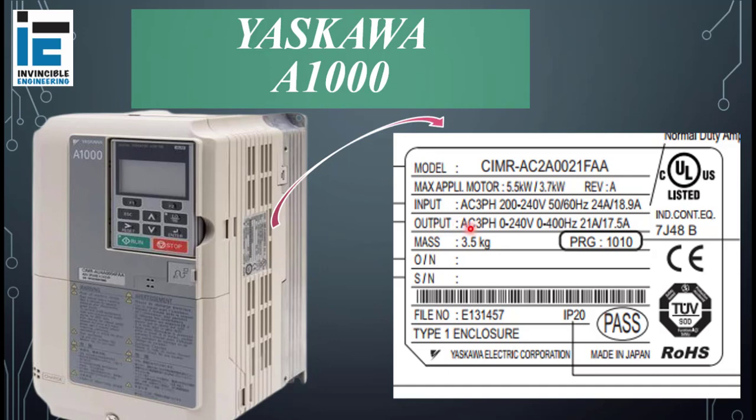The output of this inverter is 3-phase AC 0 to 240 volt and 0 to 400 Hz. The output ampere rating is 21 ampere. It means we can draw a maximum of 21 ampere from its output. Voltage can be controlled from 0 to 240 and frequency from 0 to 400. You can change it by programming.